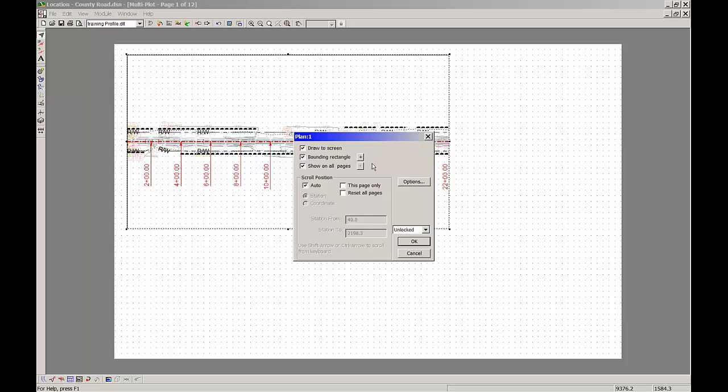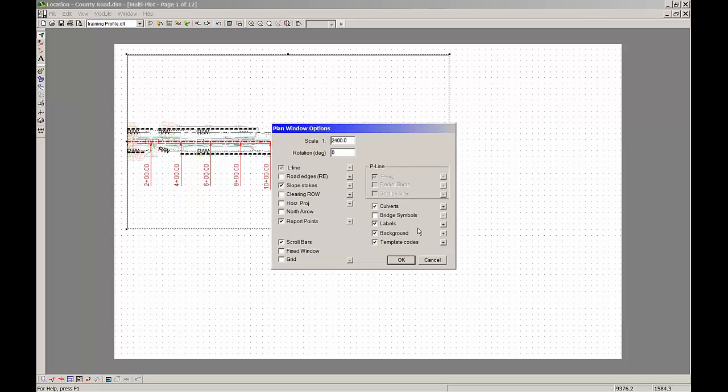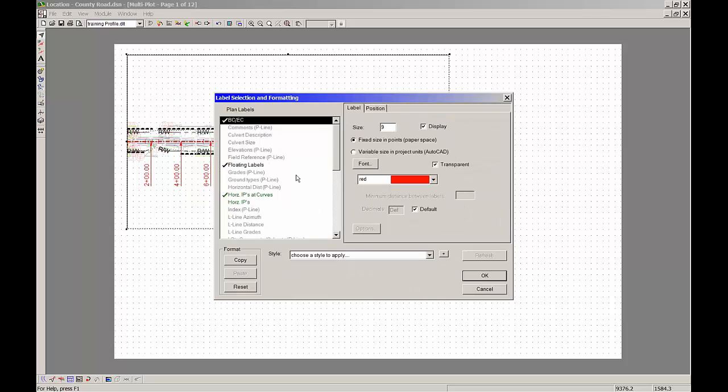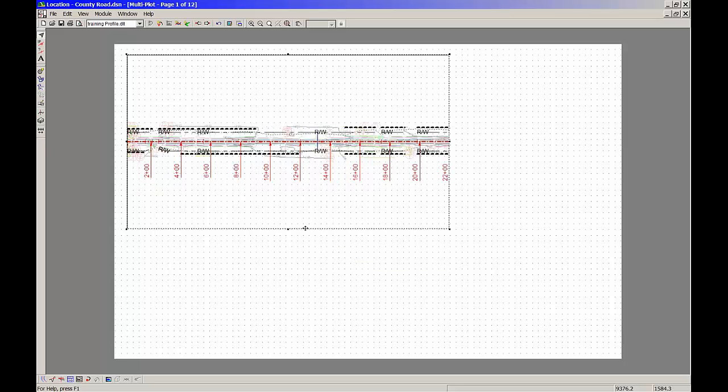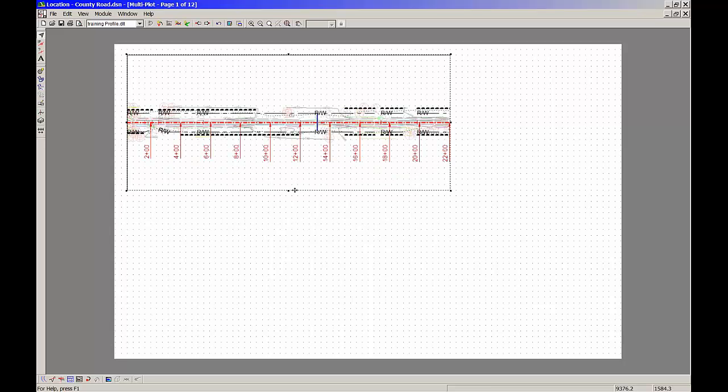One thing I'm going to also do, go back there really quickly, change my decimals to something a little bit more reasonable. Turn off default. I want 0 decimals. Make this a little bit smaller. If you happen to have noticed, my scale is at 1 inch equals 2400 inches on the ground.